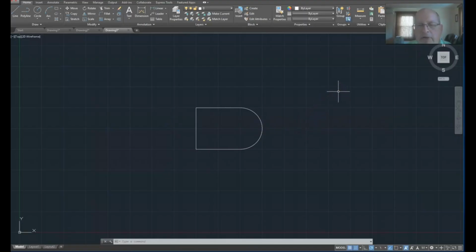What I would like to do now is to show you how to add the circle to indicate a NAND gate. Remember, a NAND gate is drawn just like an AND, but we have a circle on the output. Well, the circle is also up in the upper left. So I click on circle, and the default circle says I should specify the center of the circle and then the radius. So I'm going to choose right in the center of the output side. I'm going to choose a dot there.